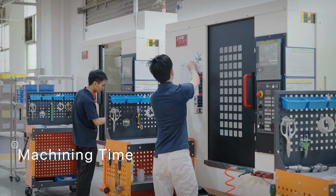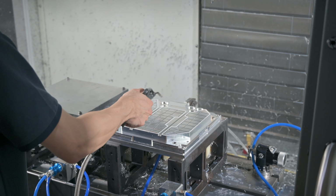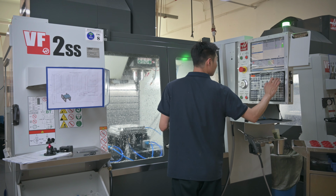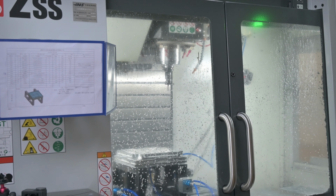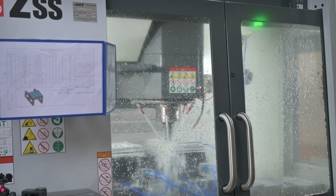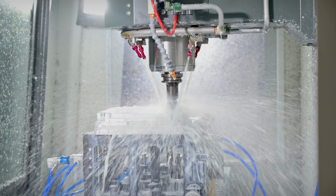Next, let's talk about machining time. In fact, the biggest factor affecting machining time is the part structure. Designers usually aim to simplify the part structure as much as possible. This helps avoid the need to frequently change tools or adjust the part setup angles on the machine during machining, which leads to longer processing times.